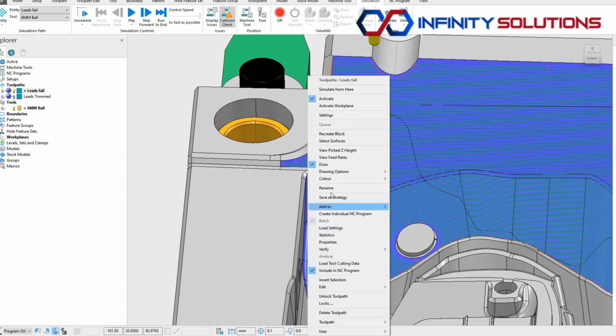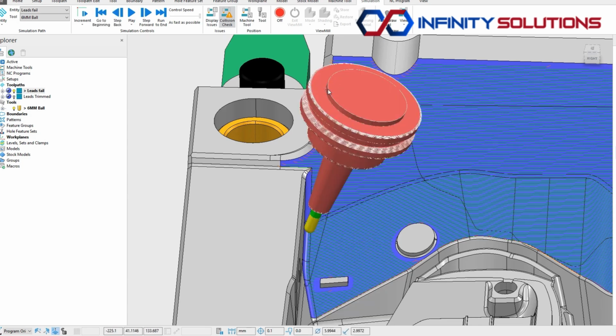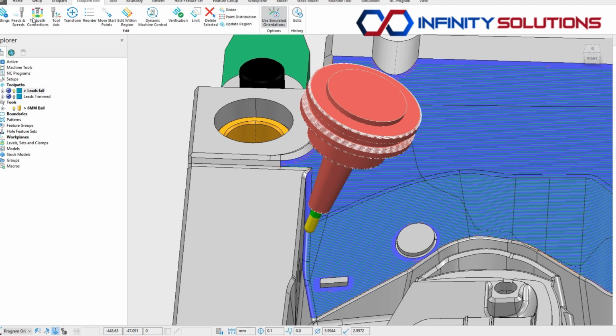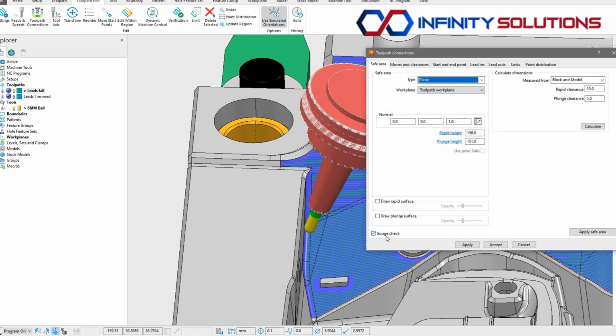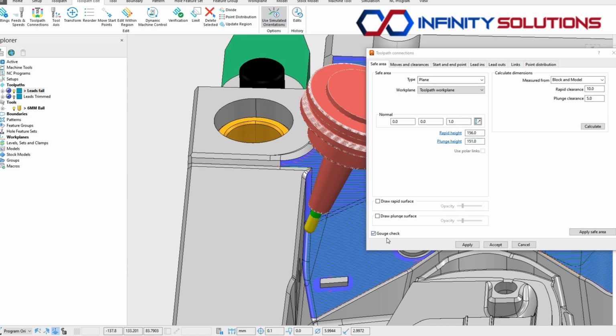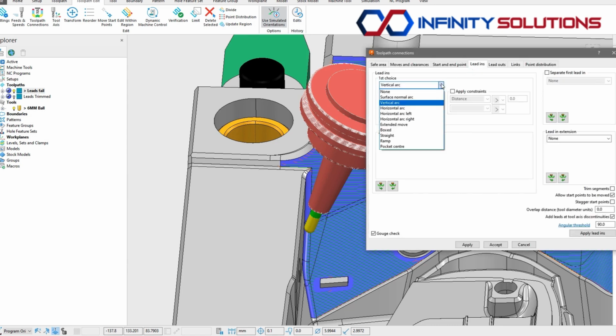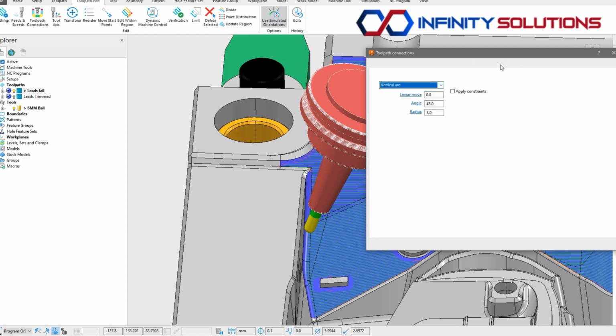By attaching the tool to the toolpath segment, notice at the end of the segment the tool is close to geometry, which in this case is a vertical wall, which does not allow enough room to apply the selected leads without gouging. As toolpaths are gouge checked during calculation, the only safe option is for PowerMill to not apply leads in these areas. We can try to resolve this by experimenting with other lead options, which may or may not give the desired result.